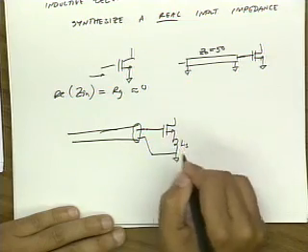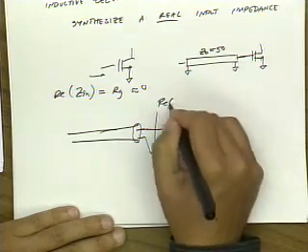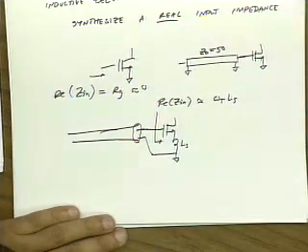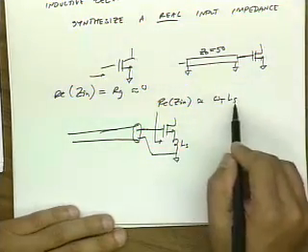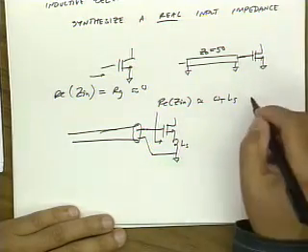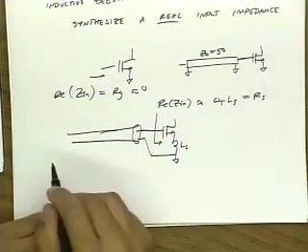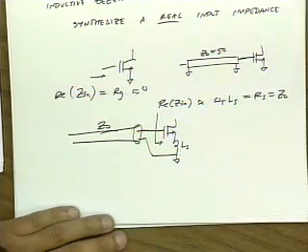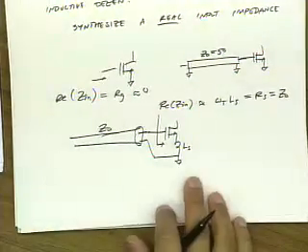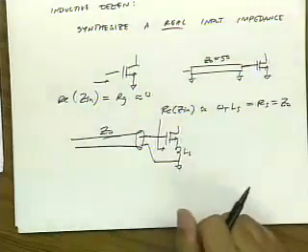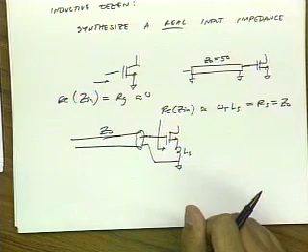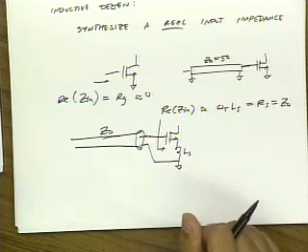So this is Ls. Now looking into here, the real part of Zin is approximately omega T Ls. So I can make Ls large enough so that this product is exactly equal to Rs, or let's say Z0 in the case of a transmission line. Okay. Now we're going to talk more about designing amplifiers that provide an input match, but this is kind of a preview of what we're going to do. Okay. Questions or comments?